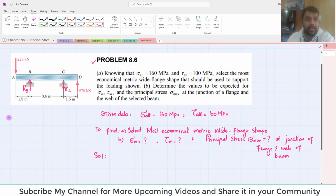So we will apply the equilibrium condition, that the sum of all moments about any point is zero. Here we are going to take moments about point C, taking the counterclockwise moment as positive. The moment about point C is due to this force, which is 275, and the perpendicular distance is 1.5 plus 3.6, which is equal to 5.1 meter. As it is producing counterclockwise, it will be positive. The second force which produces moment about point C is RB, and it is producing clockwise, so it will be negative: RB into 3.6. The third force which produces moment about point C is this 275 into 1.5, and again it is producing counterclockwise, so it will be positive. Their sum must be equal to 0.